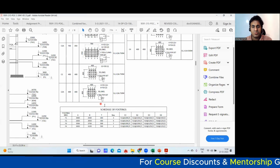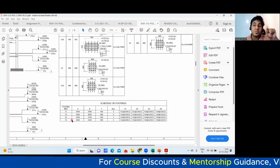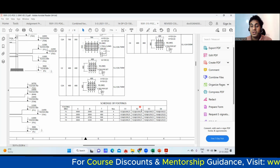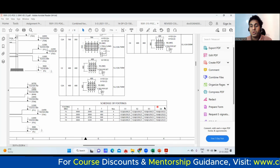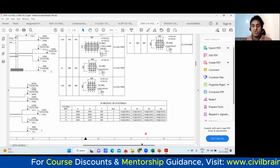Again, this is another industrial building, because whenever you find isolated footing, it is F1, F2, F3, F4. If it is combined, it will be CF1, CF2. It's isolated, but you are getting bottom reinforcement shorter span, longer, top reinforcement shorter, top reinforcement longer. Done. If you want, you can do BBS for this also, so that you don't have any doubt.